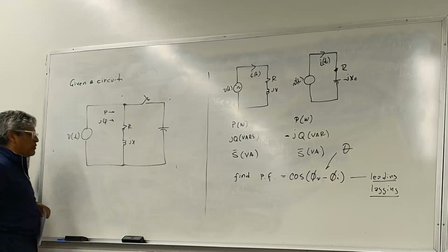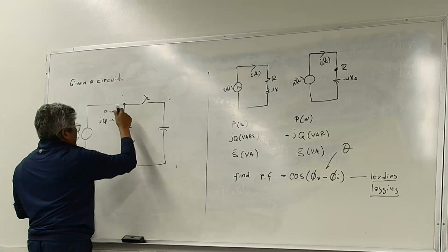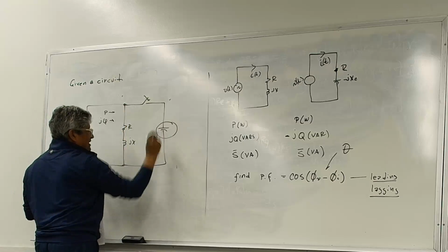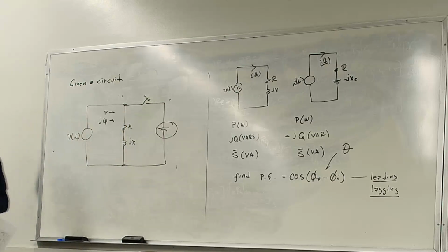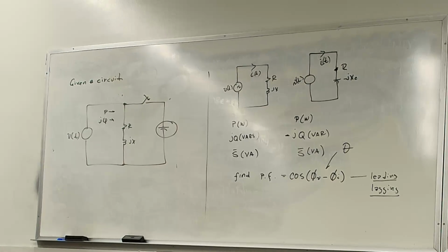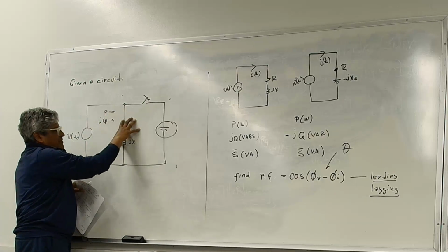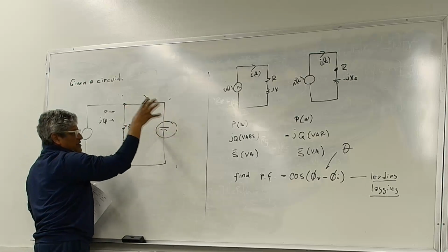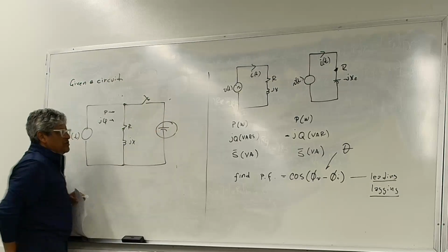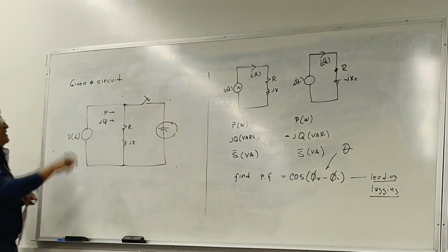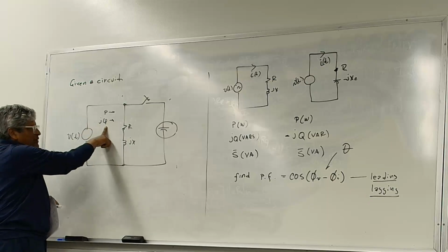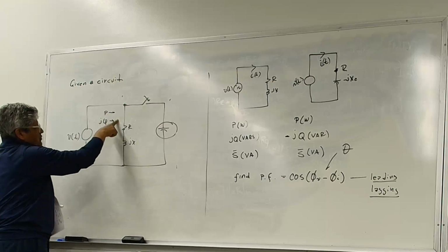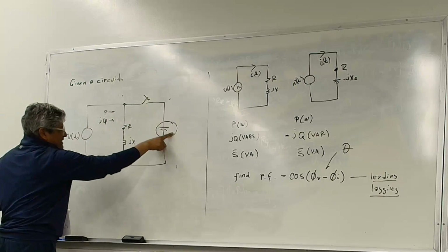Say for instance you have a low power factor, you should be able to improve the power factor using a capacitor. On that one, when I solve a couple of problems on the board, you're more than welcome to write on the cheat sheet the steps that you need to take. First, find the real power, then find the new power factor. With the new power factor, I find the new angle. With the new angle, I find the Q that is going to be supplied, and the original Q minus the new Q gives me the Q of the cap.